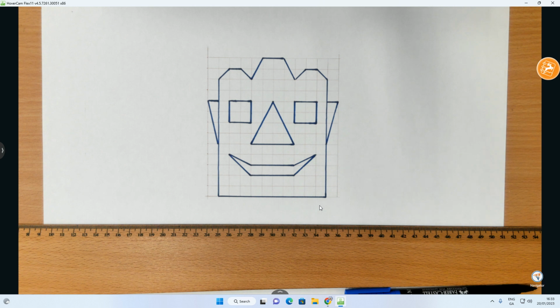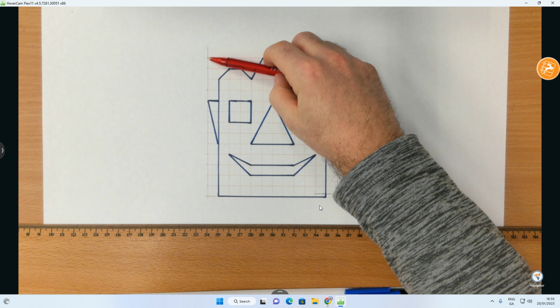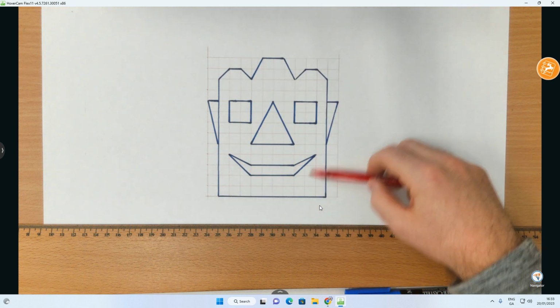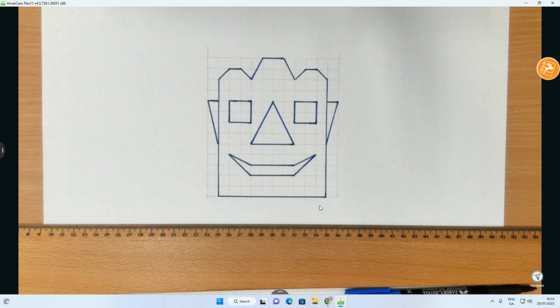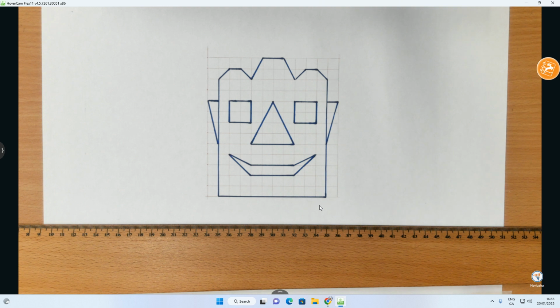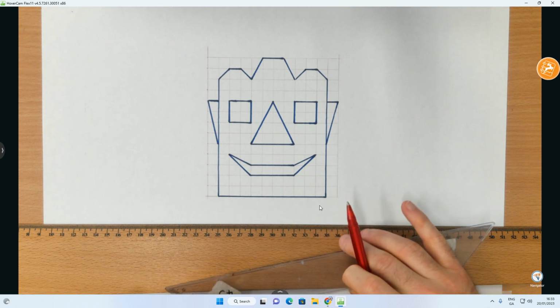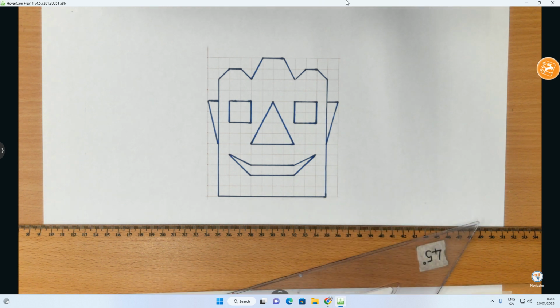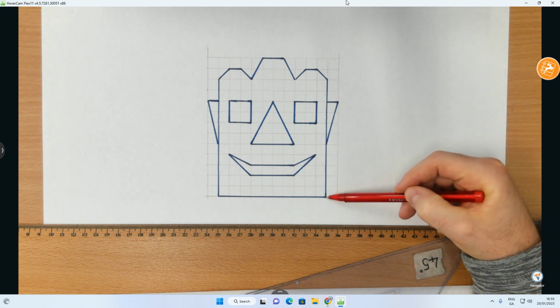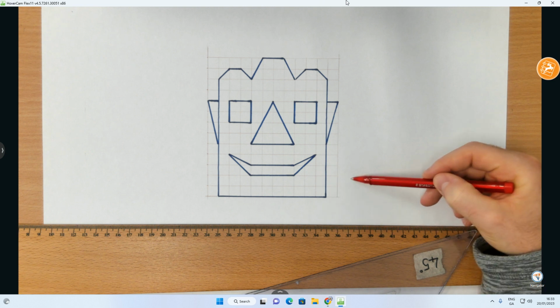If I refer to my object, you can see I've previously already done the box, where I've done 130 high, 120 long, and 10 by 10 by 10 by 10, and then I input the information. Now, to complete this question I want to project it at an angle of 45 degrees and 20 millimeters. So any edges or points that I have on the drawing are going to project back at 45 degrees.